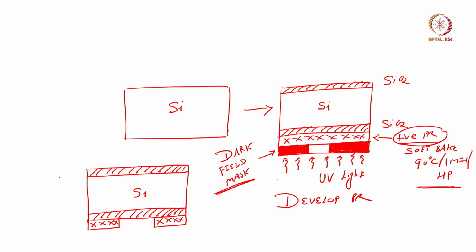So, silicon dioxide is thermally grown silicon dioxide about 1 micron, and for devices, for biosensors or for MEMS based devices, generally we go for wet oxidation. Wet oxidation is faster compared to dry oxidation. This is our photoresist. After this we need to perform hard bake. Before hard bake, I will protect the other side also with photoresist.